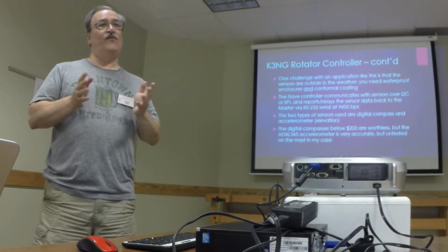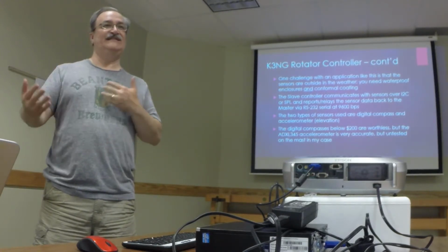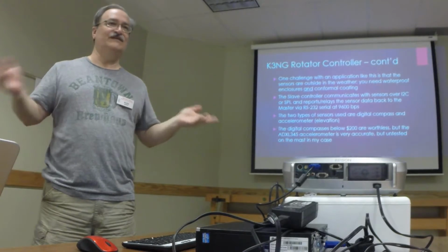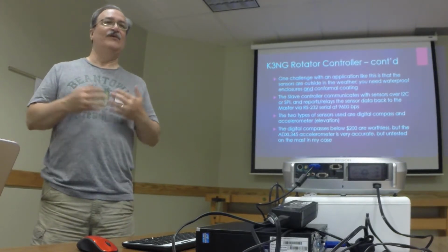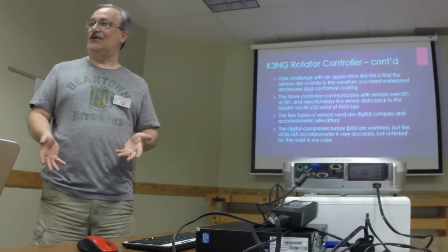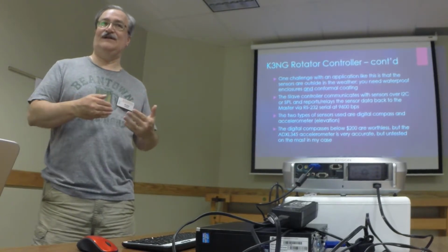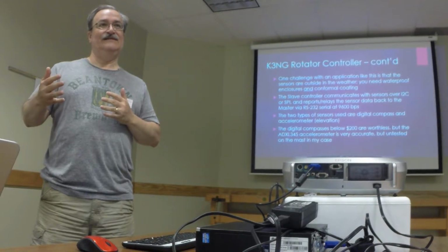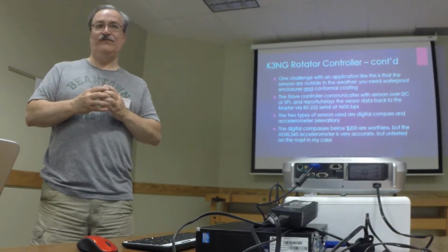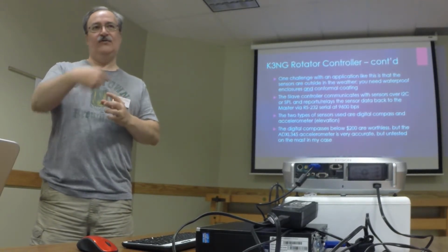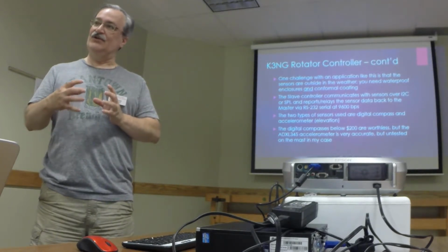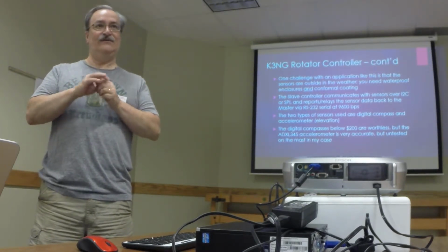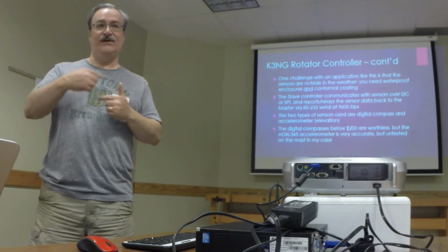And for initial prototyping or just seeing how something works, there's nothing special you have to do. But if you're going to have it out there any length of time at all in service, then you're going to have it in an IP6X kind of container that's waterproof. All your connections out of that container are going to have to be good. They're going to have a bladder or something that's going to seal that or be caulked.